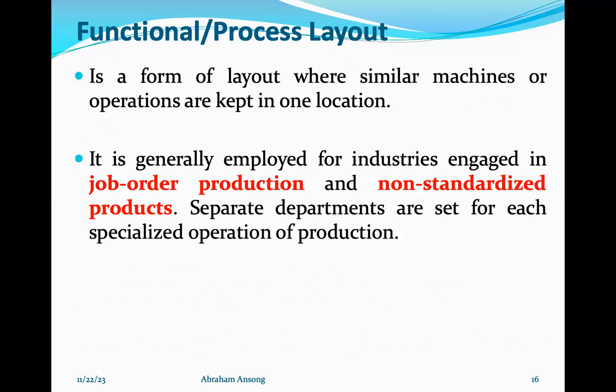With functional or process layout, it's a form of layout where similar machines or operations are kept in one location. Everything about that particular function is brought together under one location. It is generally employed for industries engaged in job order production and non-standardized products. Separate departments are set up for each specialized operation of production.